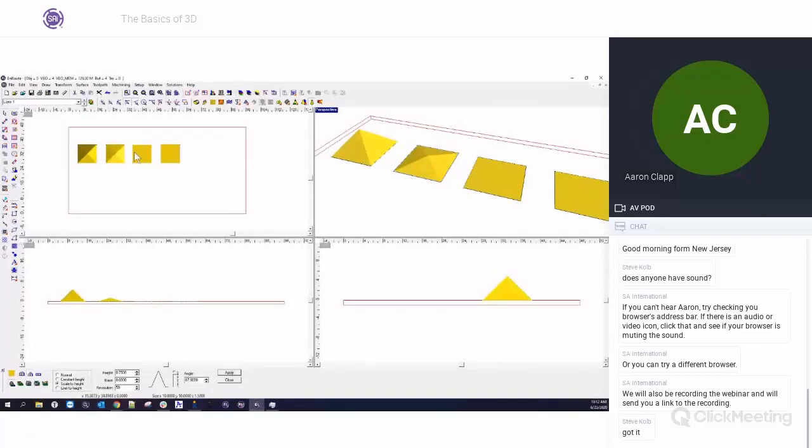So let's select our third object and hit apply. I think I actually applied a double to that one, so I don't want to do that. Okay, so you can see what it did here. It's basically the exact same shape. Now, in this particular case, this is not a difficult shape, but depending on what you're trying to do, you may not want something to be created at full size and then squashed down. That's the big difference between constant height and scaled to height.